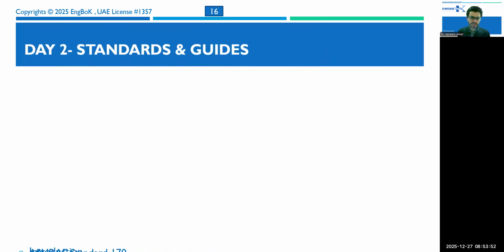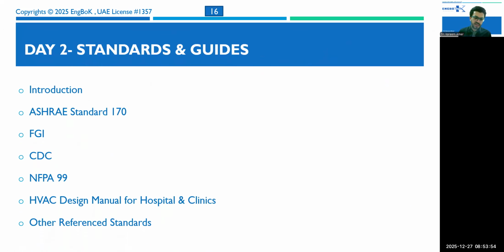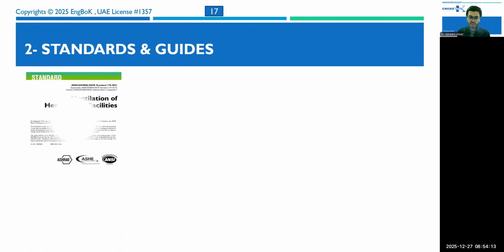Second day is about standards and guides: ASHRAE Standard 170, FGI guidelines, CDC, NFPA 99, the HVAC design manual for healthcare for hospital and clinic, and other references like NFPA 101, 72, 13, 55, and ASHRAE standards like 15 and 34, 55, 90.1, 62.1.